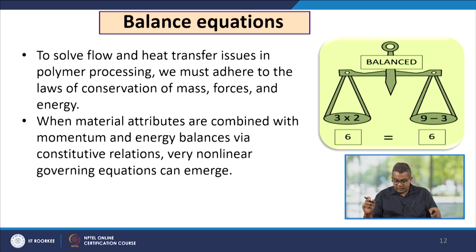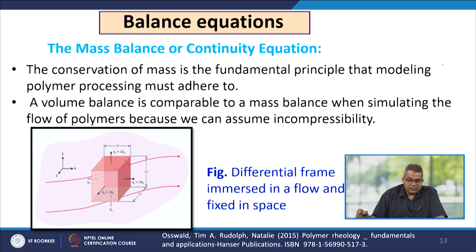Now to solve the flow and heat transfer issues in polymer processing, we must adhere to the laws of conservation of mass, force and energy. Now, when material attributes are combined with momentum and energy balances via constitutive relations, a very non-linear governing equation can emerge.